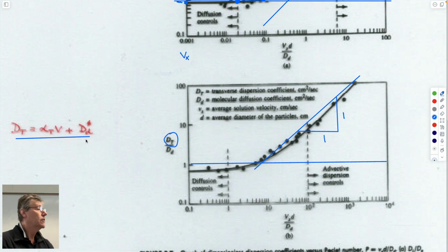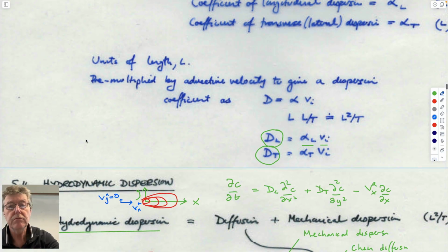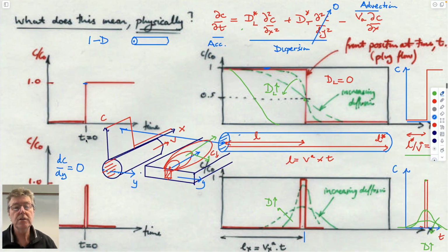Okay. That's it. So, to backtrack, forget everything you knew about multiphase flow. We're dealing only with stuff dissolved in the aqueous phase now. We need to use Darcy's law to say how quickly that moves downstream. And if we know that, and we know what the concentration that's carried in it is, we can say something about what the arrival time and what the distribution along the aquifer would look like. And we can say something about that distribution in terms of the coefficients which control its behavior, in terms of advective transport and diffusive transport.